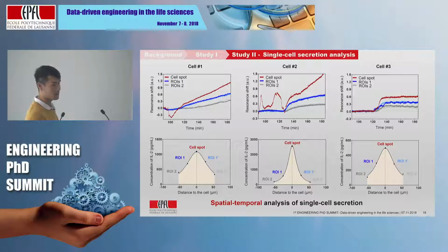Thank you for your presentation. I'm wondering about the fabrication of the chip, with the beautiful nanopore. The fabrication is, we can use E-beam or deep UV lithography. The advantage of deep UV lithography is we can pattern the nanoholes over the whole wafer scale, for large-scale production. With E-beam, it's time consuming and you need to do it point by point.